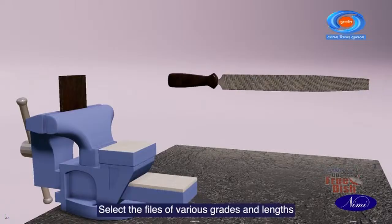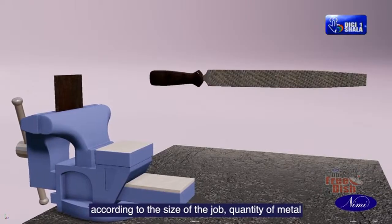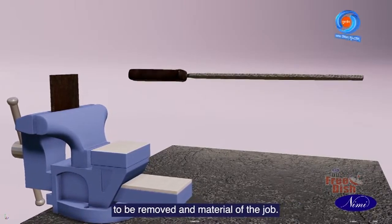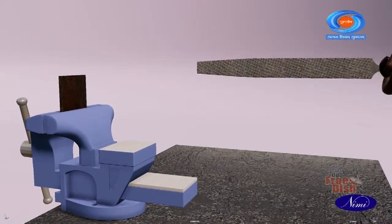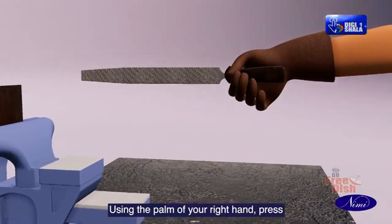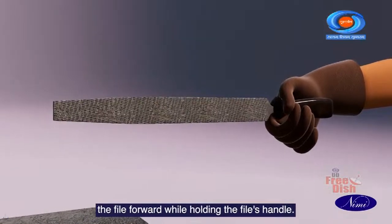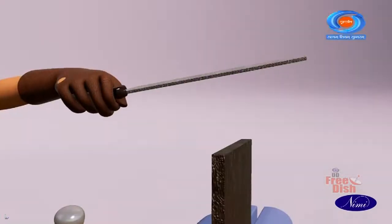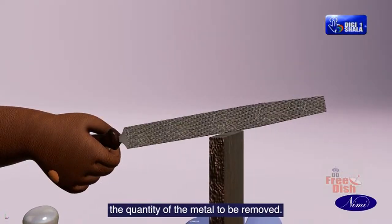Select the files of various grades and lengths according to the size of the job, quantity of metal to be removed, and material of the job. Verify that the file's handle fits tightly. Using the palm of your right hand, press the file forward while holding the file's handle. Hold the tip of the file according to the quantity of the metal to be removed.